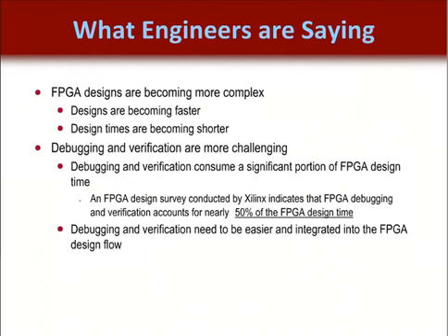To help improve design time, Xilinx recommends the use of its ChipScope Pro software. This enables die-level testing of a design by applying stimulus to internal nodes of a design and then retrieving the resulting signals using the ChipScope cores built with FPGA resources. To do in-circuit verification with ChipScope, you will apply stimulus to many nodes in the FPGA and store the generated signals using FPGA block RAM as well as other logic resources inside the FPGA. The generated results can then be displayed with a ChipScope Pro logic analyzer. This allows you to quickly verify the operation of many nodes and verify the operation of your device in circuit.